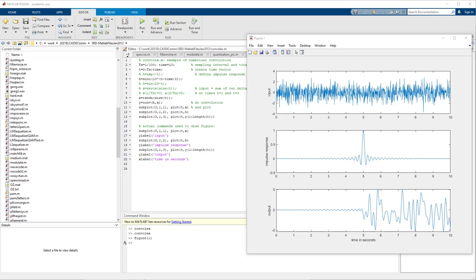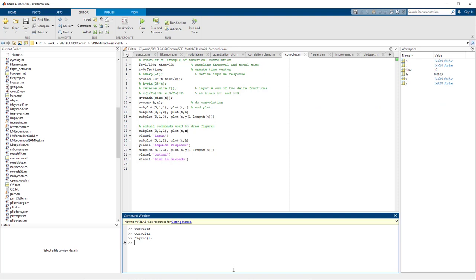Now I want to see the channel effect of this sinc function. A sinc function in the time domain gives a low-pass filter in the frequency domain. Basically, a sinc function in the time domain is a rectangular function in the frequency domain. The rectangular function will filter out out-of-band frequencies. So let's look at the spectrum of that.